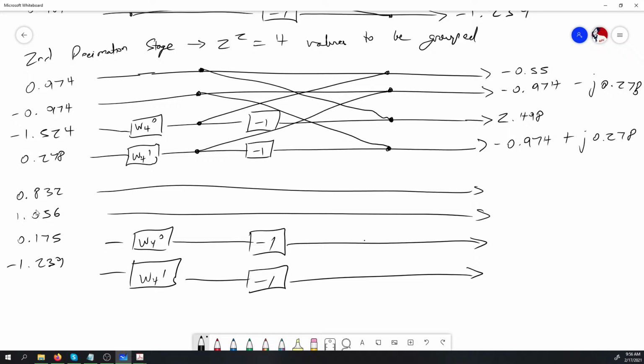So in this next grouping of 4, the first value here must map to the first value with a twiddle factor. So just repeating that, the first value here that doesn't have a twiddle factor must map to the first value that does have a twiddle factor. Put our cross point here, go to the first value with a twiddle factor. Similarly, put a cross point here, go to the value that didn't have the twiddle factor, and then we calculate out accordingly for this butterfly as such.